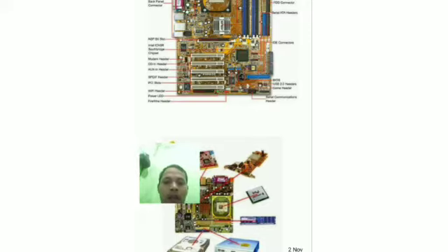Then read the mainboard manual book first so you know where the jumper will be. A jumper is a small component that is placed on the mainboard to control the CPU and the voltage that enters the mainboard. Wrong jumper settings can result in damage to the processor. So be careful when installing this jumper by making sure you attach it correctly.